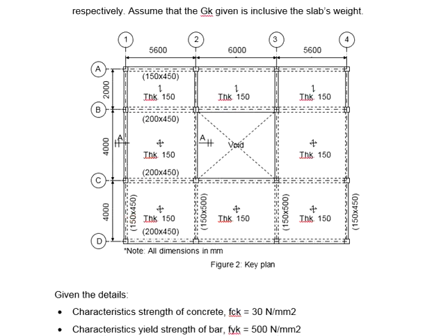The meaning of two-way slab is that the loads acting onto the slab are distributed to all four sides of the beams. As for the one-way slab, you will assume half of the loads goes to one side and another half goes to the other side. As for the beams at the shorter spans, you will assume not carrying any load.